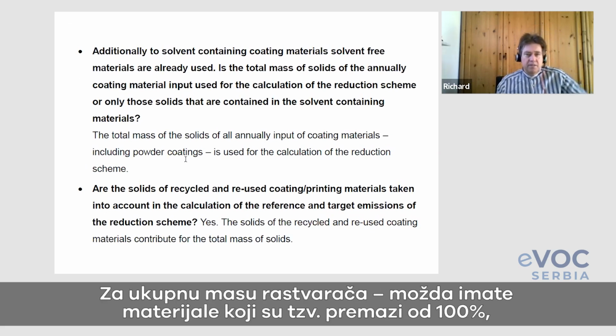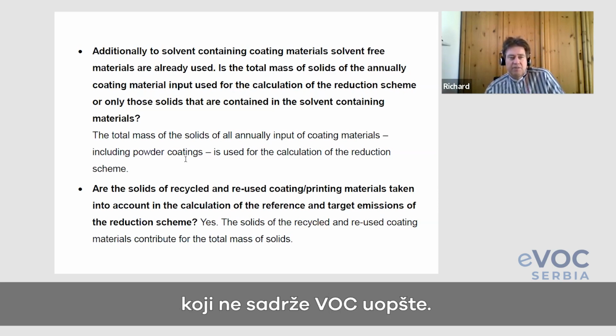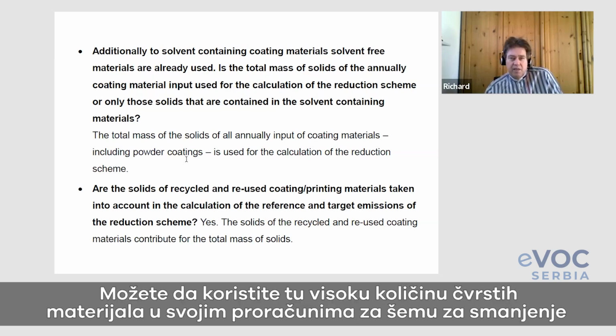For the total mass of solids, of course, maybe you have materials that are so-called 100% coatings. That means they don't contain VOC in the printing materials. But of course, because you do something good, you can use that high quantity of solids in the calculation for the reduction scheme.